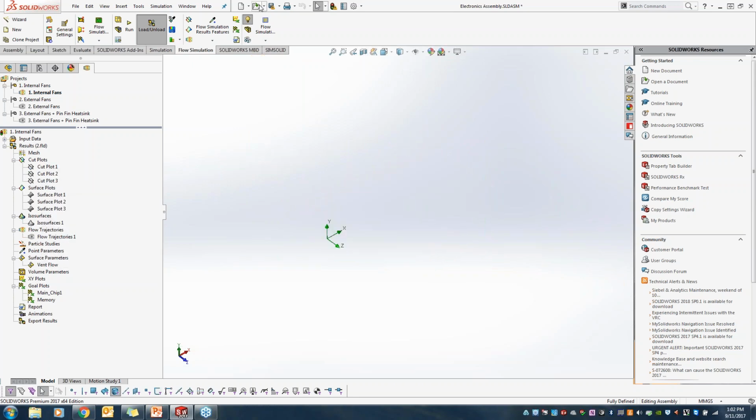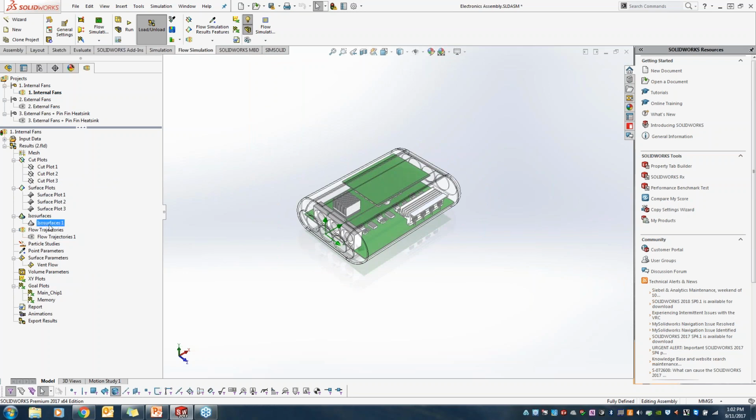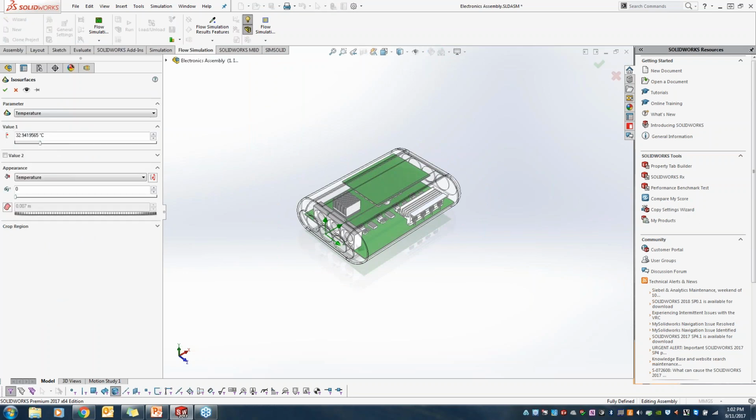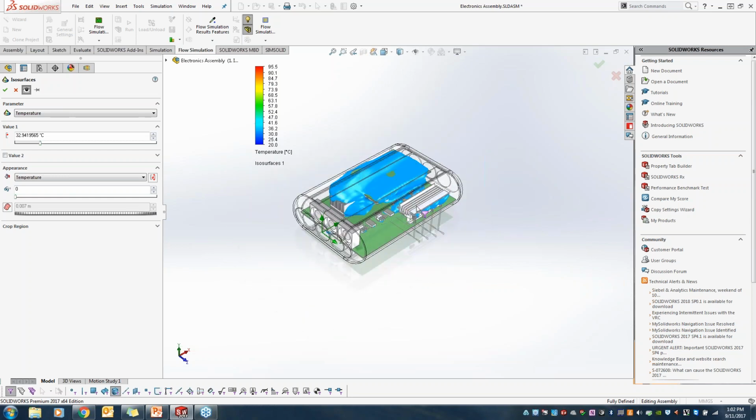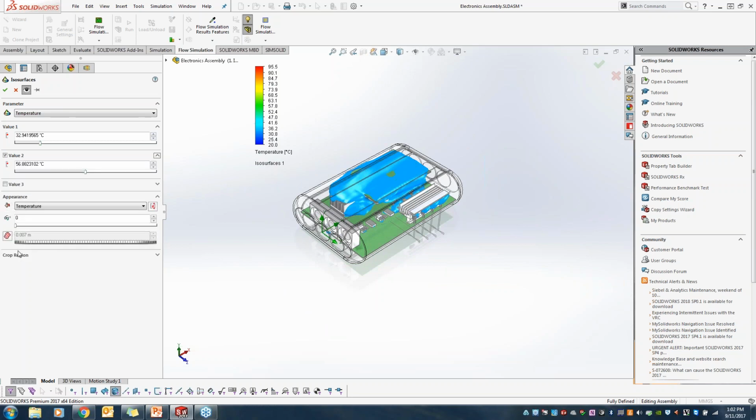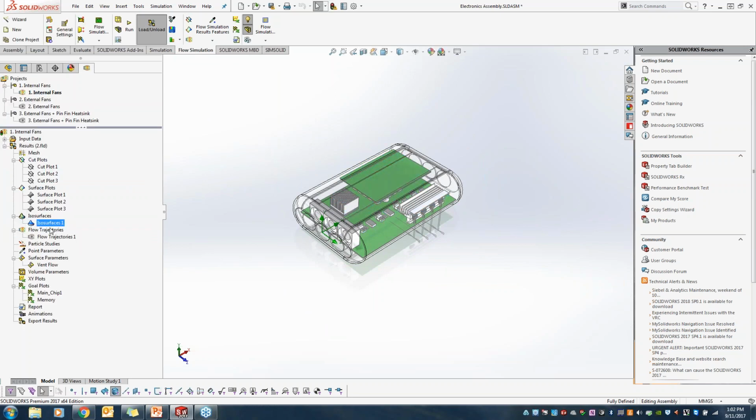The other thing we can create as a plot is isosurfaces, means I would like to see the volume or the places which temperature is 32, and here it is. It can show me where and in which region I have those kind of temperature, and you can add more and more and have more and more isolation and see the critical area for yourself. Next type of